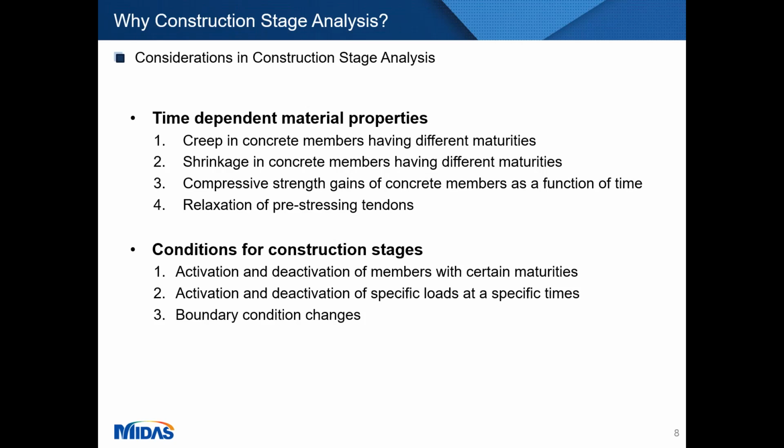So suppose a load is activated at the 0th day of construction and another at the 20th day of construction. Both will be different cases, as the strength of concrete will be different at both steps.